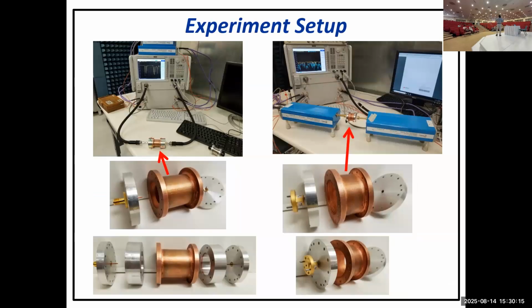E-band wavelength is 4 millimeters probably, or maybe less. The period of this is lambda, so the period is lambda over 2, so 2 millimeter period basically. Around lambda over 2, not exact. So look, this is the first passband, second passband, if you take a look at the VNA measurements.